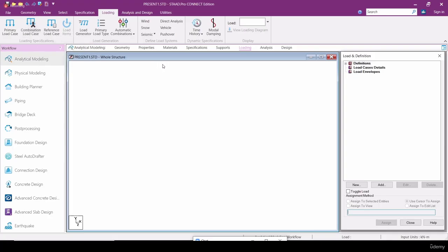You have to design a particular structure by using load combinations only. You cannot design any structure with independent load cases. If you go to Table 4 in IS 800, you can find partial safety factors, and you have to derive the load combinations from Table 4. Every code will have certain load combinations based on its specifications, so you have to use that wherever applicable.